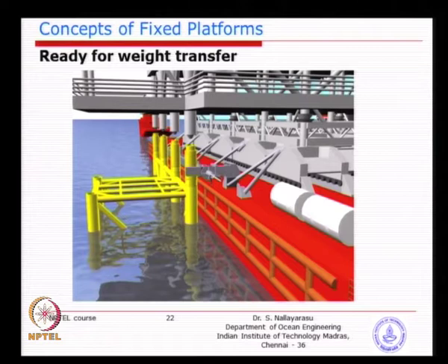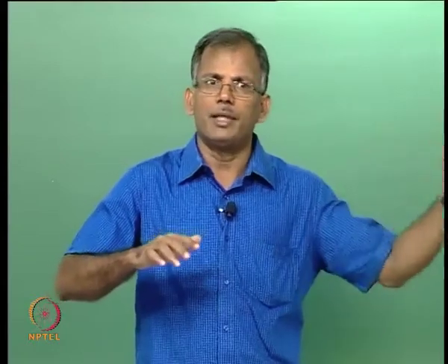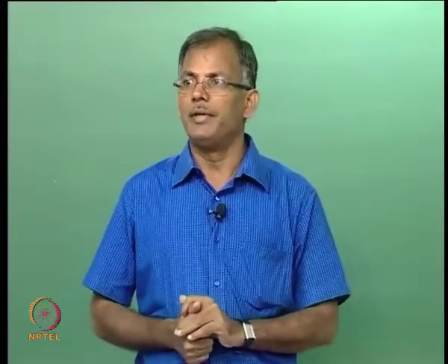So, you see here when it is just impacting like this, what will happen to the steel at this top? It may actually get damaged or locally yielded, there may be a dent. So, in order to prevent this, we need to have some active devices built in either in the lower part or in the upper part. Imagine if you put a hydraulic jack inside, what will happen? During the impact, you can activate the hydraulic jack either to extend or to retract, but the timing of activation is so difficult to determine, isn't it? We do not know, because with 8 supports, one of them may touch first because of slight tilting of the bars, the other one may not. So, this will be very difficult to manipulate.